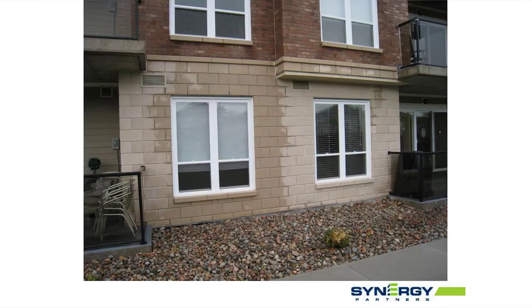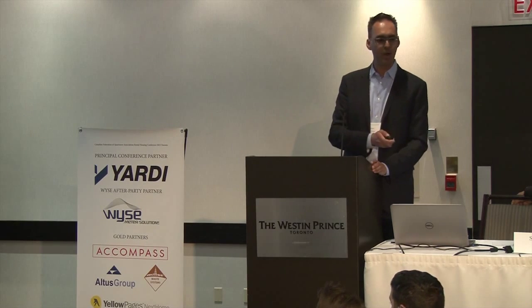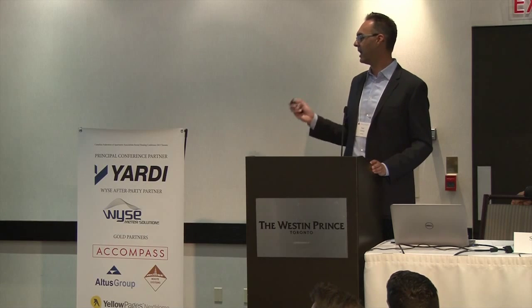There's no overhang here. There's no drip edge on this little cornice detail, and this wall is obviously getting really, really wet. And this is just detailing. And if there was a proper drip flashing, something to get the water and kick it out away from the walls, these guys are going to save themselves a lot of headaches down the line.